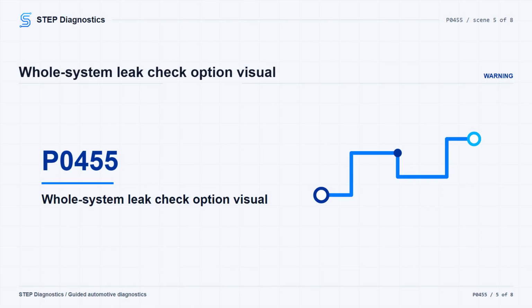Once the manual data points to a leak, choose your leak check method. One option is to test the entire EVAP system as a whole. Use kit, yield, and accessory 8404C. Connect the red lead to battery positive, the black lead to battery negative, connect shop air, set the smoke and air control to AIR, start airflow with the remote button, block the AIR supply tip while pressing the remote button, and calibrate the flow meter if needed.